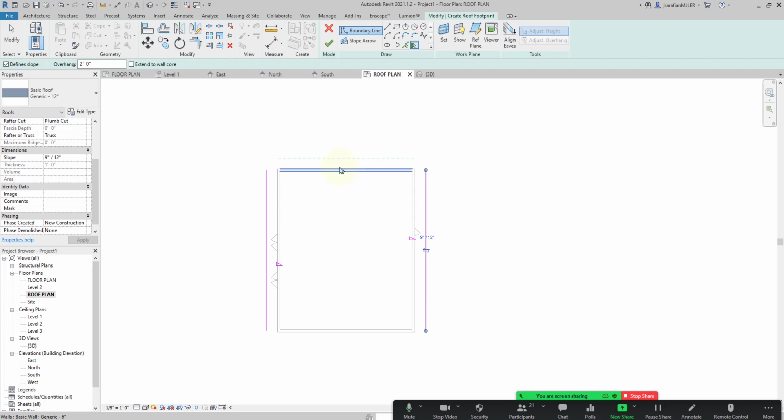If I want to create a part of the roof that doesn't have a slope, I uncheck this. So this side and this side will not have any slope. I only want a slope here and here, meaning we'll end up with a gable roof. There will be a ridge that runs down the middle of this if the slope is here and here. Opposite, right? If I wanted that ridge to run this way, I would create a slope here and a slope here.